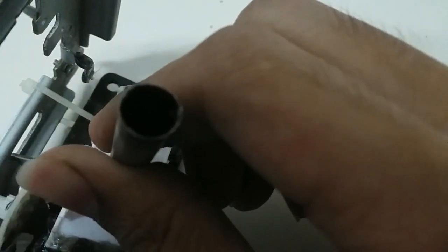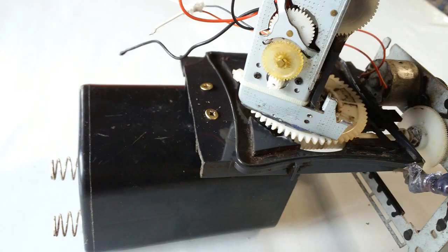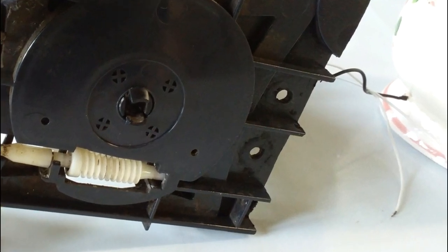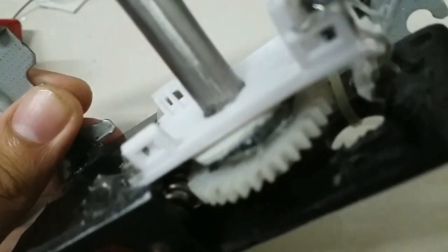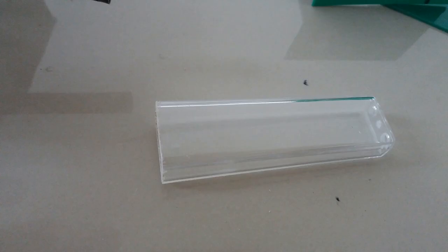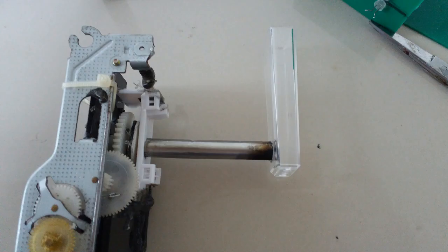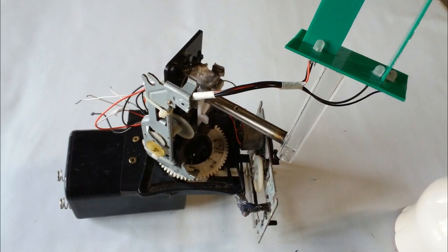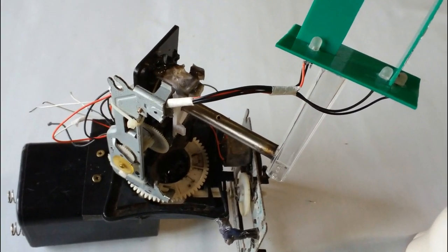I made a low RPM gear rotator system from broken DVD players. You can see the 2 worm gears on every axis. It is useful because it locks the gear connected next to it, so when the motor stops, the thing attached to it cannot rotate. I got a plastic piece here and attached it to the horizontal axis, and I glued the sensor at the top. I assembled all the parts, and there we have it.